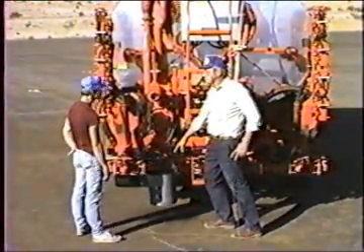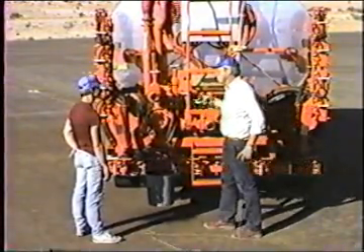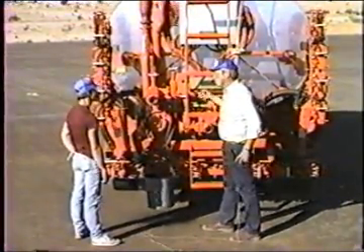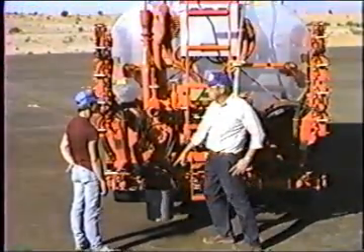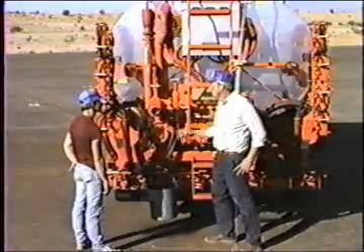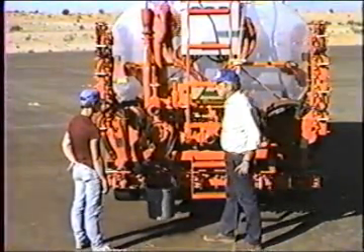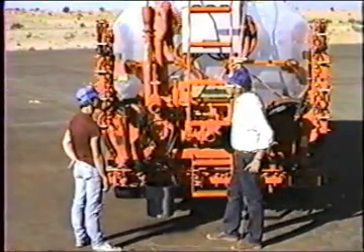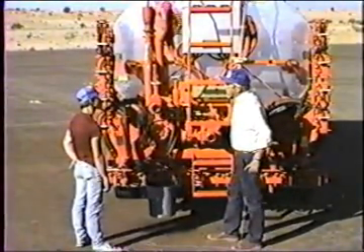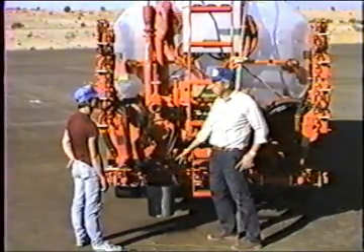Well, within just a couple minutes, we've got hot diesel here, and it goes around again. The more times it goes, the hotter it gets, and the better it washes out the asphalt. By the time we circulate that bucket for 5 minutes, this thing is clean, and the spray bar is totally flushed. Now, if we're using cutback asphalts or emulsified asphalts, it doesn't take very much time. One bucket is a great plenty.